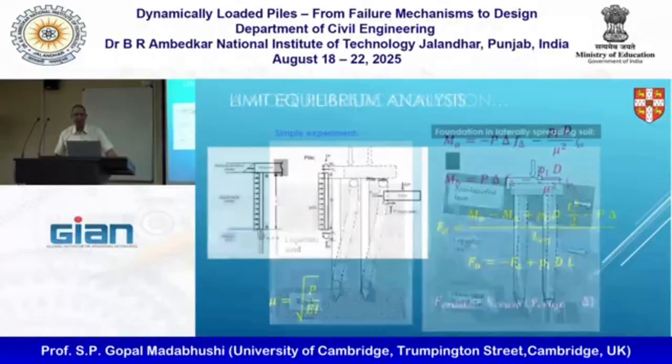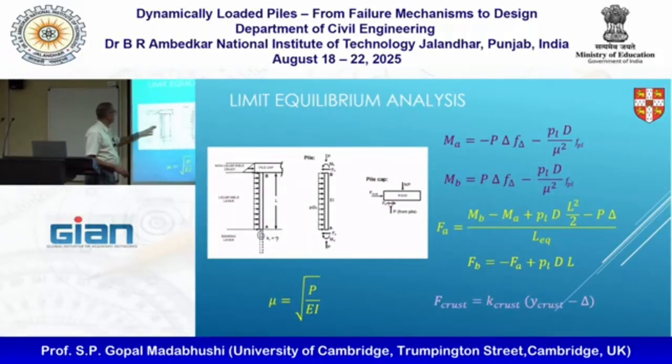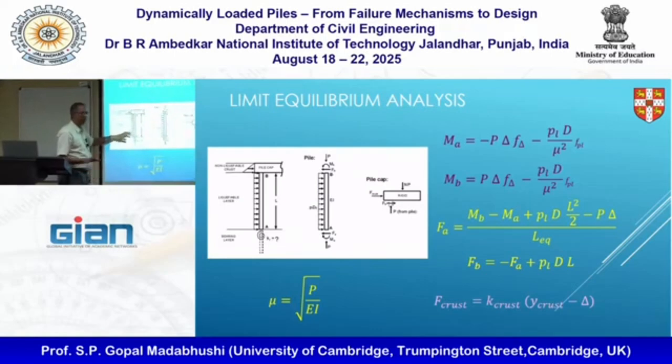And this is where we can do some fairly simple calculations. So, say you are in level ground to start with, you can say the non-liquefiable crust is going to apply the full passive pressure. For clayey soils, you know how to work out Kp. You should have done that in maybe a third year geotech or fourth year undergraduate course.